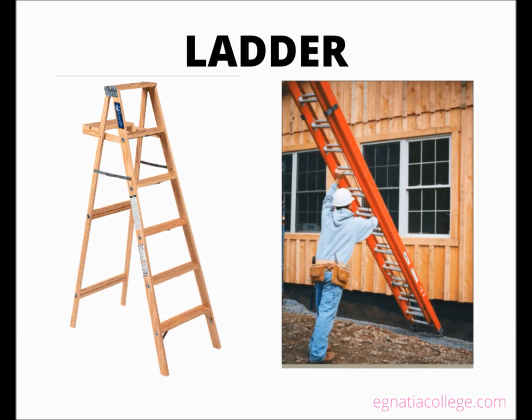Drills can react violently when an obstruction is encountered, causing loss of balance. Stepladders, usually 6 feet or 8 feet for residential construction, are usually intended for interior work. A worker should not stand on the top of a stepladder; it violates regulations. All ladders have a maximum weight limit, so the weight of materials and tools must be calculated with your body weight as the total weight load.